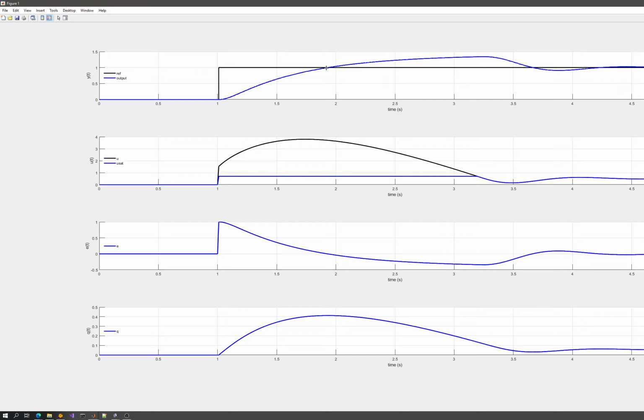and this limit, even though I have reached the value, is still applied. So if you think about it, if I'm at the reference, my error signal is not that high, and you can see that here. It's in fact almost zero or around the vicinity, but my control signal is very high, and my raw control signal, which is black, at this point has a peak which is between 3 and 4. So it's 3.7 approximately at this point. So why does this happen? Why do I have this sort of behavior?